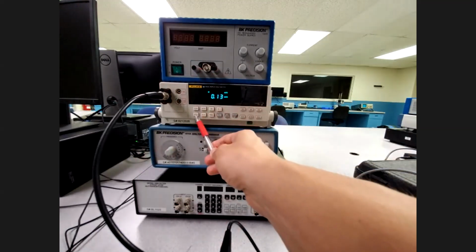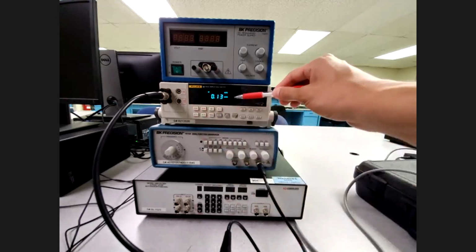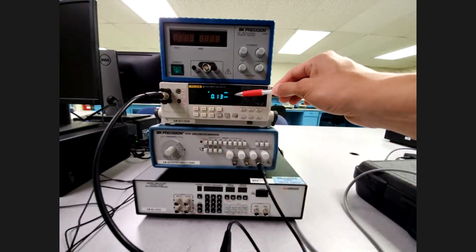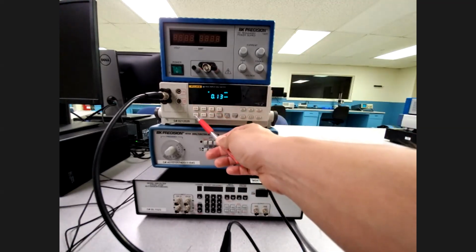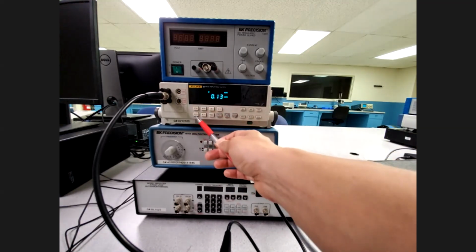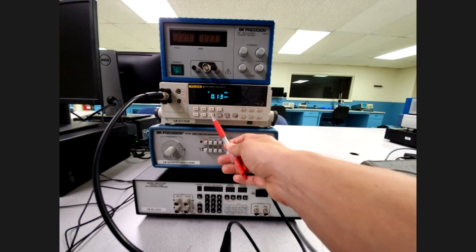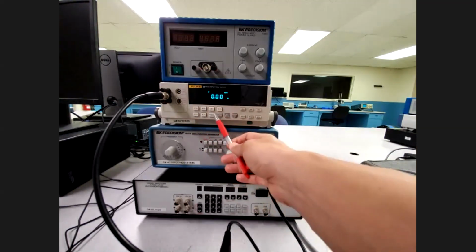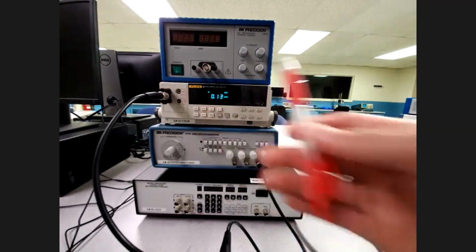And right here, I'm going to set it to voltage RMS. Remember, everything coming from the multimeter is going to be a signal quantity in RMS. For this experiment, we're going to be switching from voltage RMS with this button at the bottom left corner, and also the frequency. We're going to be toggling between the frequency option and voltage RMS option for the AC signal.